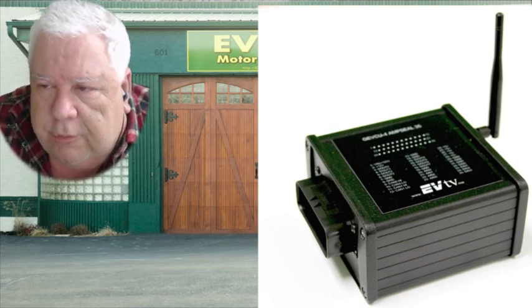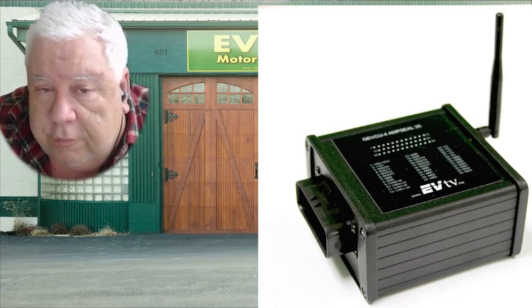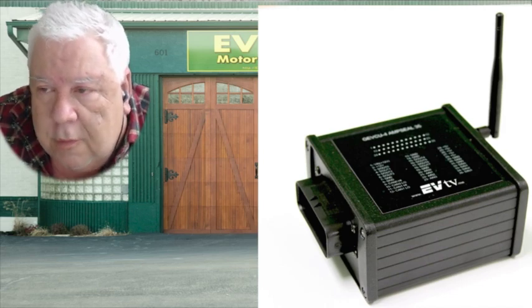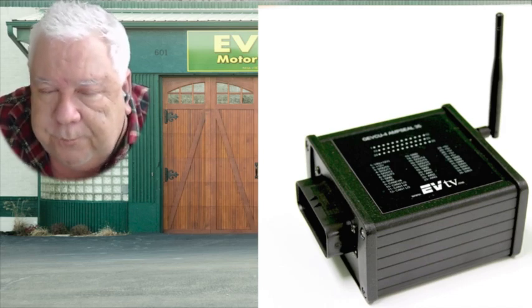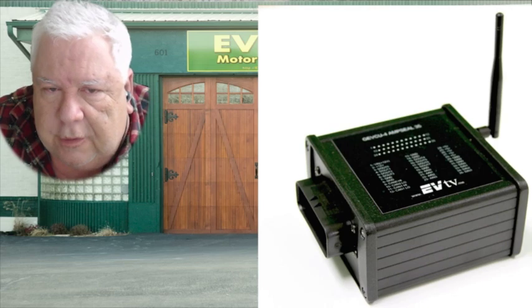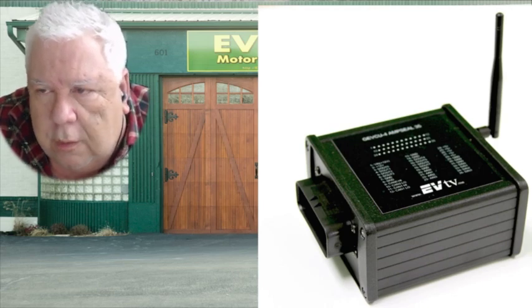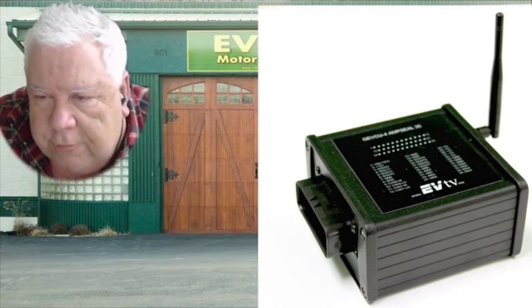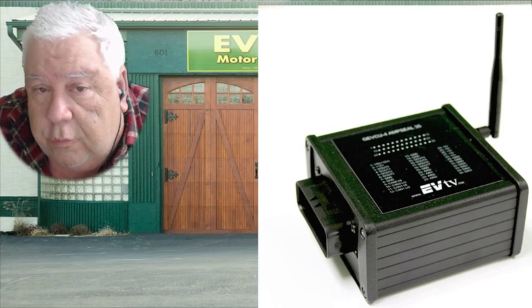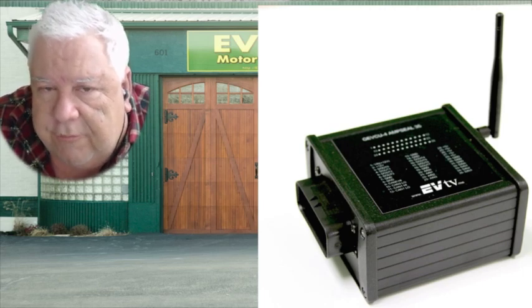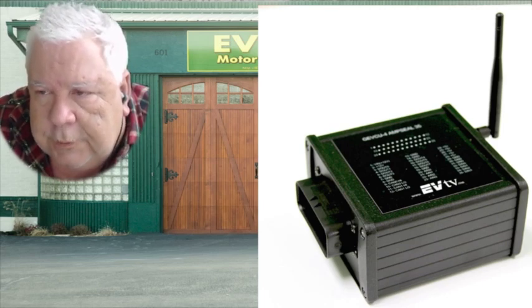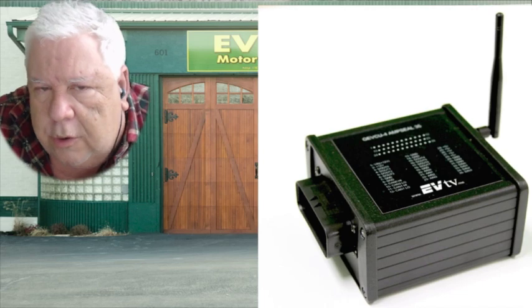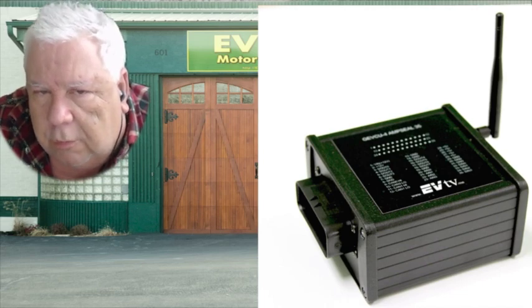And so we developed the GEVCU to do just that, to provide two interfaces, one by wireless website and another with a basic USB serial port command interface, where you can make changes to the crucial variables determining vehicle operation and kind of tune your inverter and controller to the specific vehicle application you had.